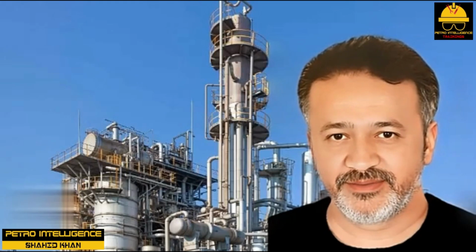The Reboiler. All machines have drivers. An internal combustion engine drives a car. Pumps are driven by turbines or motors. Jet planes are pushed by the thrust of an axial air compressor. A distillation column is also a machine, driven by a reboiler. It is the heat duty of the reboiler, supplemented by the heat content, enthalpy, of the feed, that provides the energy to make a split between light and heavy components.